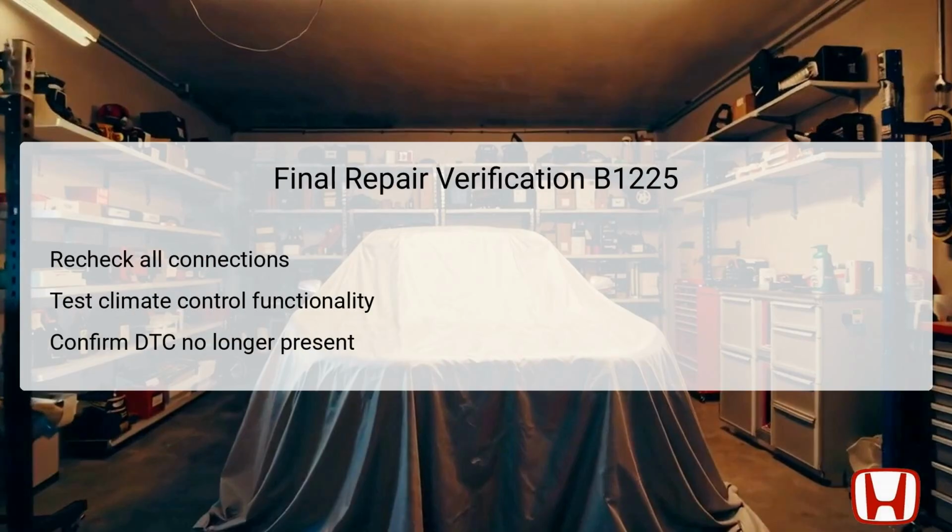After completing all necessary repairs, the final repair verification step is crucial for confirming the success of your work on DTC B1225. Begin by rechecking all connectors and wire connections to ensure they are properly secured and free from any corrosion or physical damage. After ensuring the connections are solid, perform a functional test on the climate control system to verify it is operating as intended.